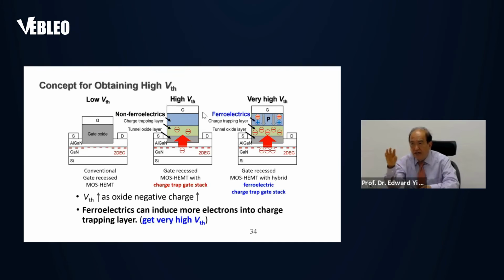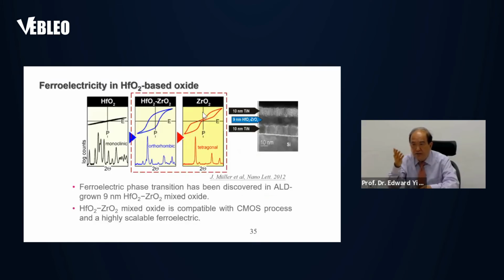Okay, so that's the idea, the beauty of the ferroelectric type of gate stack. Okay, so the ferroelectric here just gives you a very high VTH.